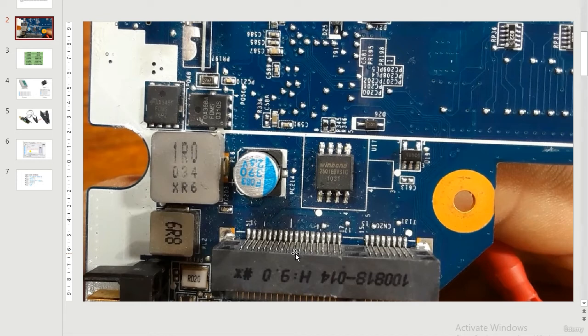All chips, no heat, no hot chip, all components seem to be good. The motherboard is not broken. You check the connectors, you find that all the connectors are not damaged. All voltages are present, but the problem is still here. The motherboard is dead, which means 100% you should reprogram the BIOS. You have a corrupted file inside the BIOS.